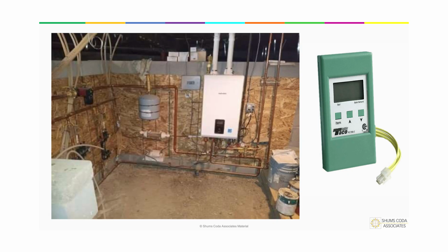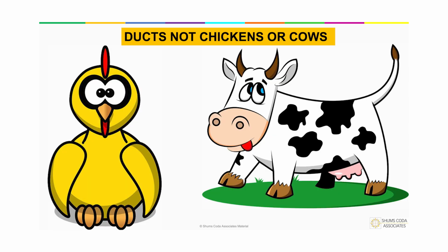Make sense? It's kind of like how we have set points for furnaces and so forth, where there's a temperature of 5-degree difference between the two of them so that the heating doesn't kick on at the same time that the cooling kicks on. It's kind of that same concept, but tied to a boiler system. All right. Any questions about controls?